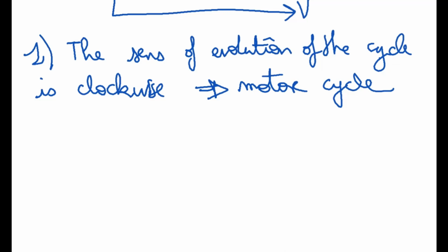So the sense behind this is the fact that if you have a system that is providing to the outside some mechanical energy, then the work is negative. Imagine that you are an operator that is on the outside. So you are in the environment and you are external to the cycle. And you are going to take the mechanical energy that the system is creating. So in your referential as operator, the mechanical energy is received, but in the referential of the system, the mechanical energy is given away to you, right? So the system is going to have a mechanical energy that is negative because it's getting out. That's the reason why for a motor cycle, W of the system is always negative. So that is the sense of a motor cycle. For you as operator, it's going to be positive, obviously, but for the cycle, it's negative.